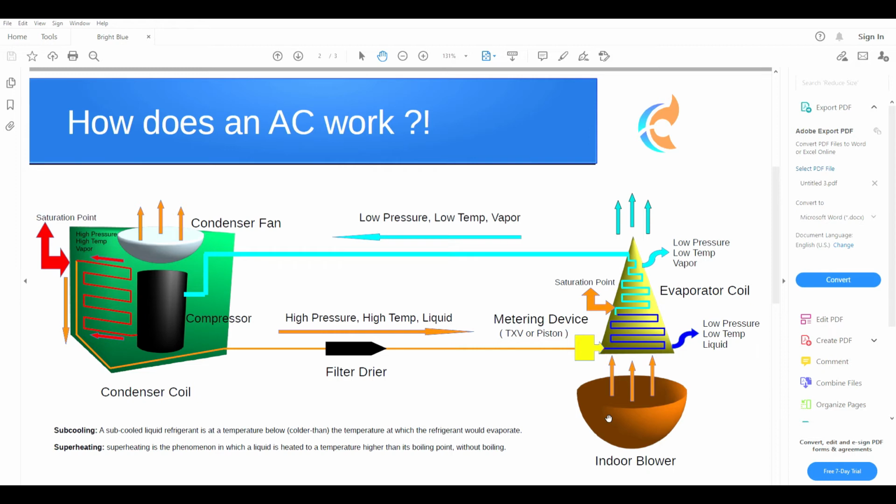The return air is coming from the house back to your air handler to be blown across the evaporator coil that you guys have here. So this air is technically the same temperature as the air inside your house, which is going to be warmer than the temperature of the refrigerant in your evaporator coil.